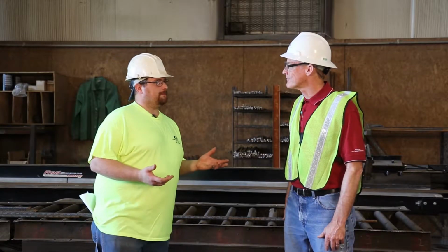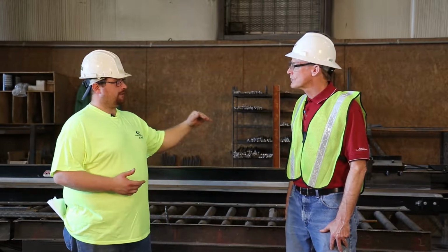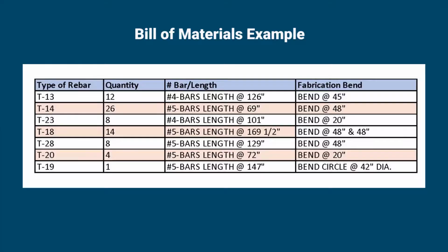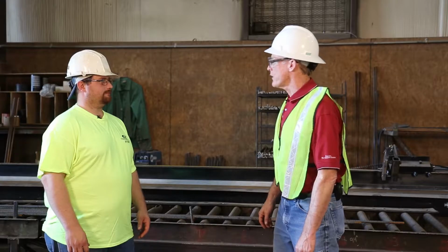And it will tell you if it is a US made or foreign made steel if your project specifications require it. So for a typical cage layout, there are straight sections and bent sections. Some shop drawings may include a bill of materials that shows the exact number of each individual rebar size and cut length. They may also show a bend detail for the precast structure, while other drawings may not. If the shop drawing does not show a reinforcing steel bill of materials, then the plant will need to develop one on their own. That's great advice, Michael.